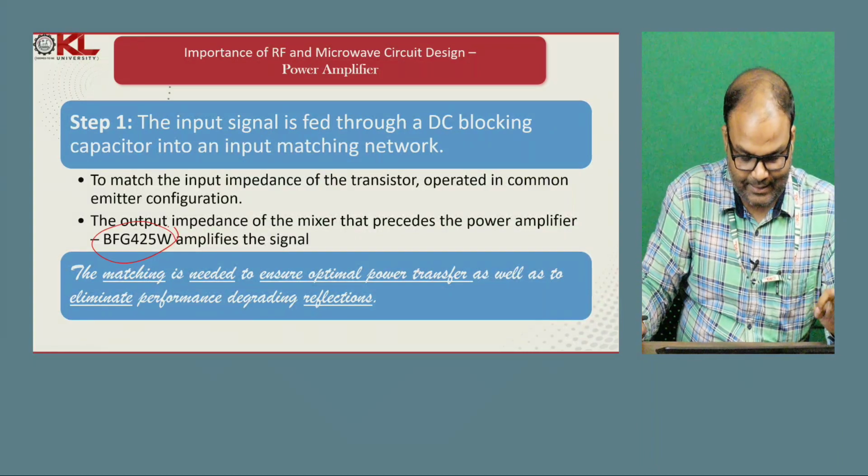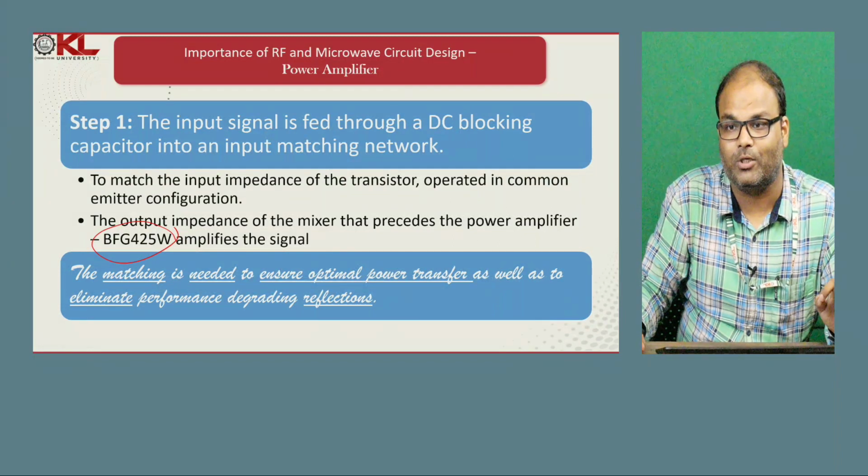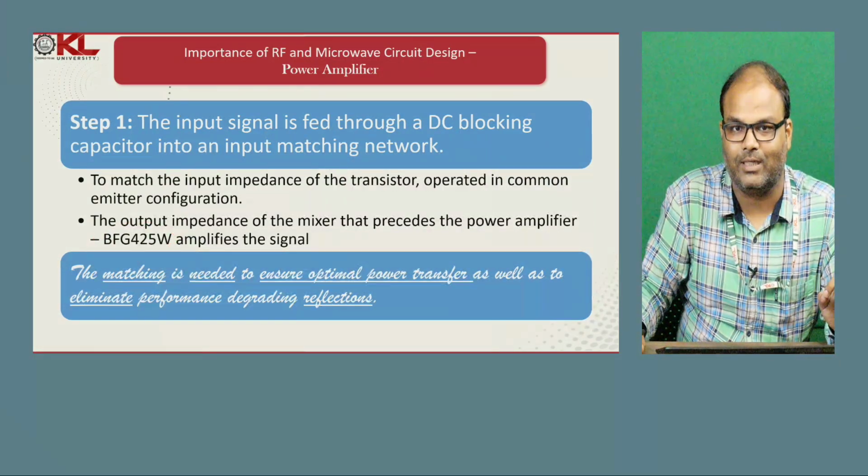So we are using this power amplifier, so the matching is needed. Why is matching needed? To ensure optimal power transfer as well as to eliminate performance degrading reflections.